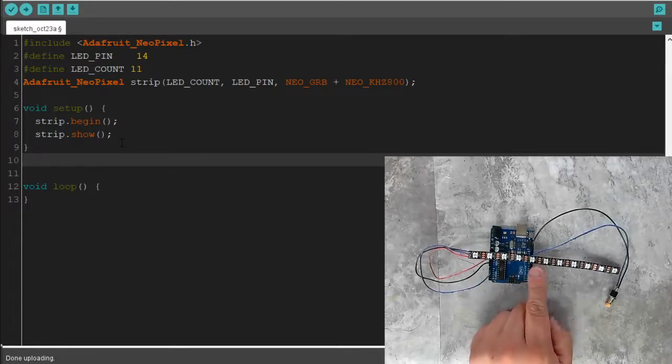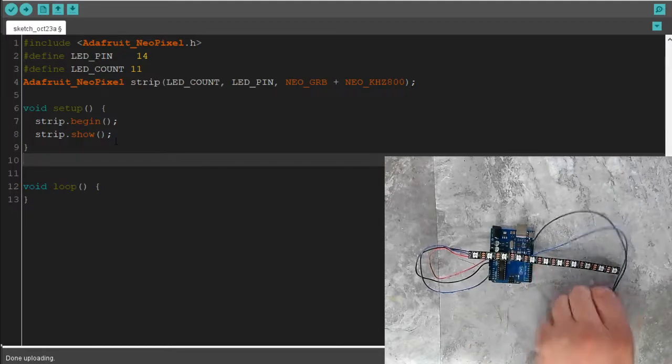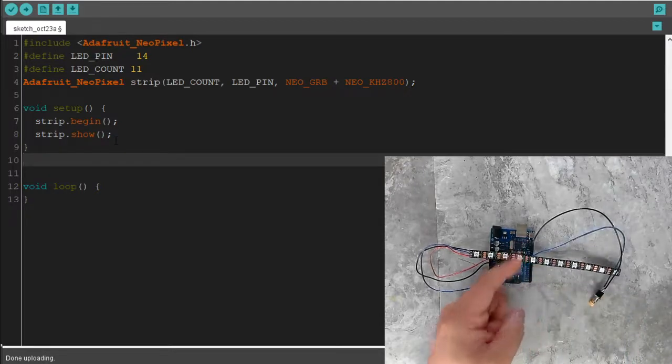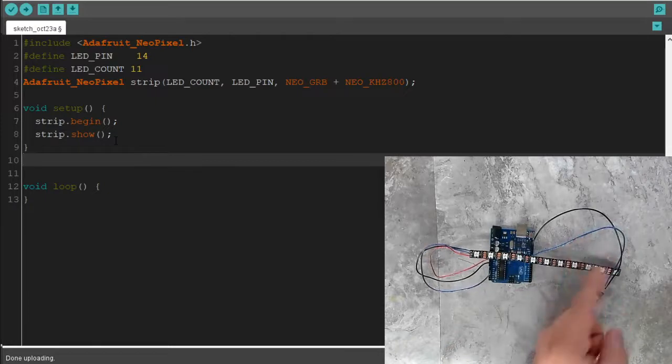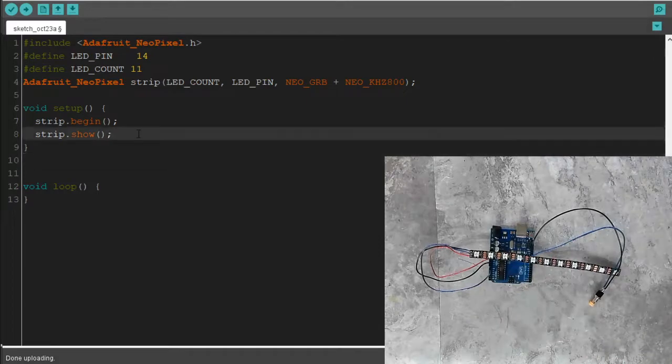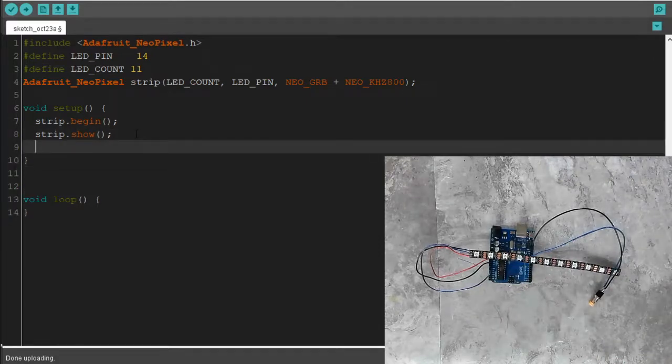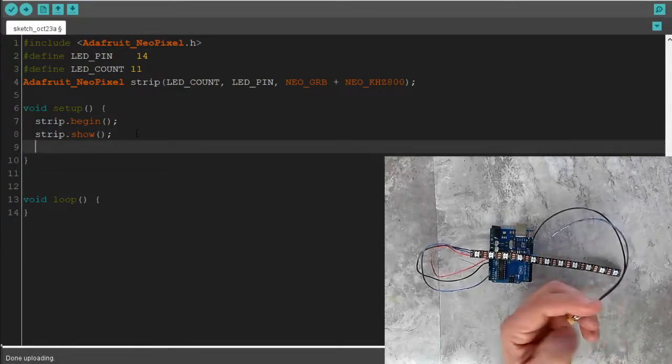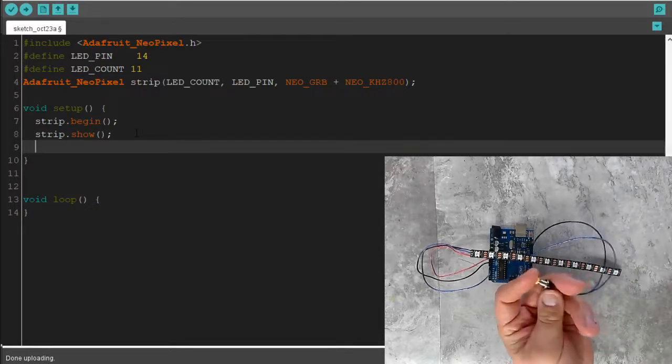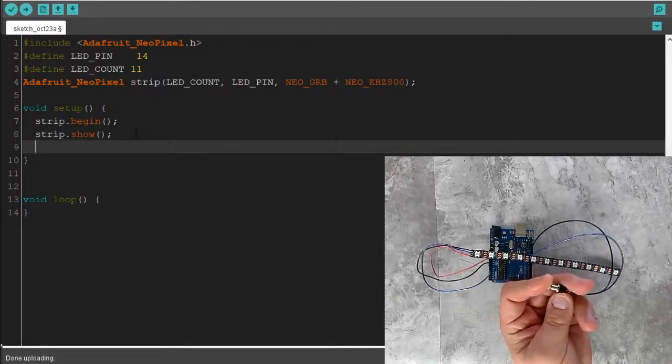So I plugged the button here into pin 12. And then there's ground right here. So what it's gonna do is connect ground to pin 12, right? It's gonna ground out that pin. So we're gonna keep that in mind. What happens if I were to push this button? It's grounded out, right? Now that pin equals low or 0 or false, whatever you want to call it.